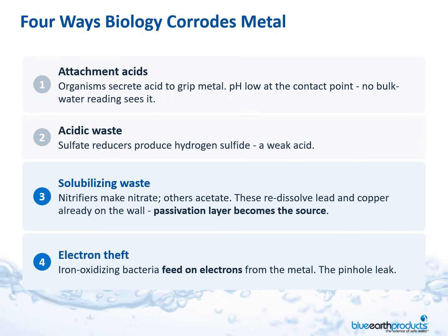And biology has multiple ways to form dissolved metals, by attachment acids or acidic waste that it produces, or it can produce solubilizing waste as part of the life cycle of the bacteria. It can pull lead or specifically copper out of the wall and result in very high levels of copper, or even electron theft, for example iron bacteria taking electrons from the metal surface.